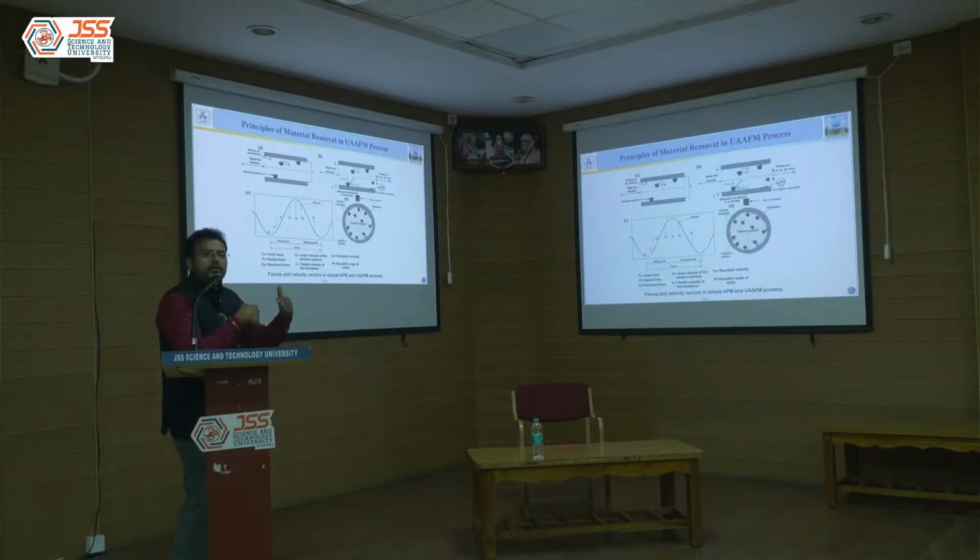If your workpiece has a larger diameter, there is a chance of abrasive particles simply rolling and sliding without targeting the surface. Those inactive particles are addressed by vibrating the workpiece.